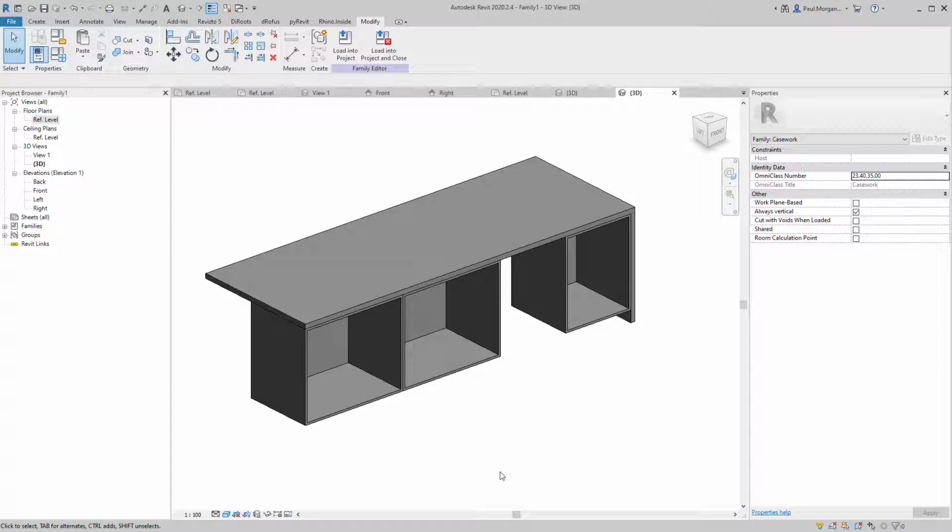And that would be very slow. So remember, a parameter is essentially a question. So I just created a question saying, what is the benchtop finish for this kitchen cabinetry? I can answer that question in the project, and then I can use the same stone as what I've applied to those other objects, those other families. And if I want to change that type of stone later, all I would have to do is go into the material editor, change the codification or change the type of stone I'm using for the benchtop finish, and that will update everywhere else. So that's why we use parameters and answer the question, particularly materials wise, inside of the project.